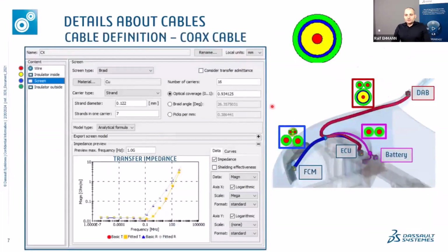So of course, in CST the user normally sees the cable cross section imported from CATIA, for example, from CATIA electric design, but the user also has the huge freedom and flexibility to interact with those wires here and create their own. For example, I think it's most often the case that the user wants to play with the shields of the components.